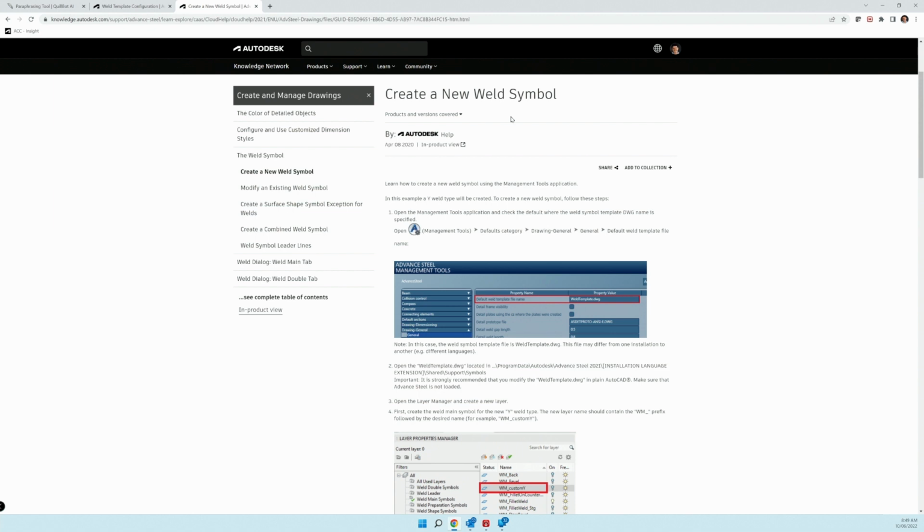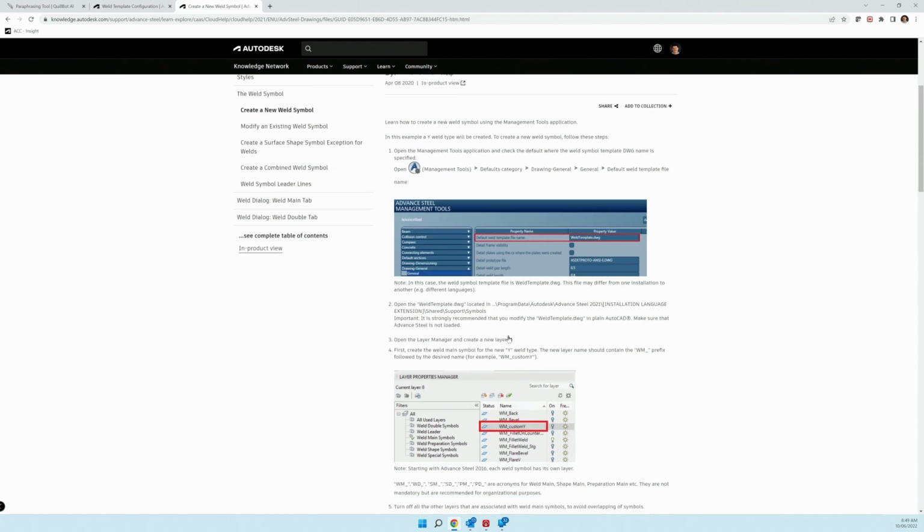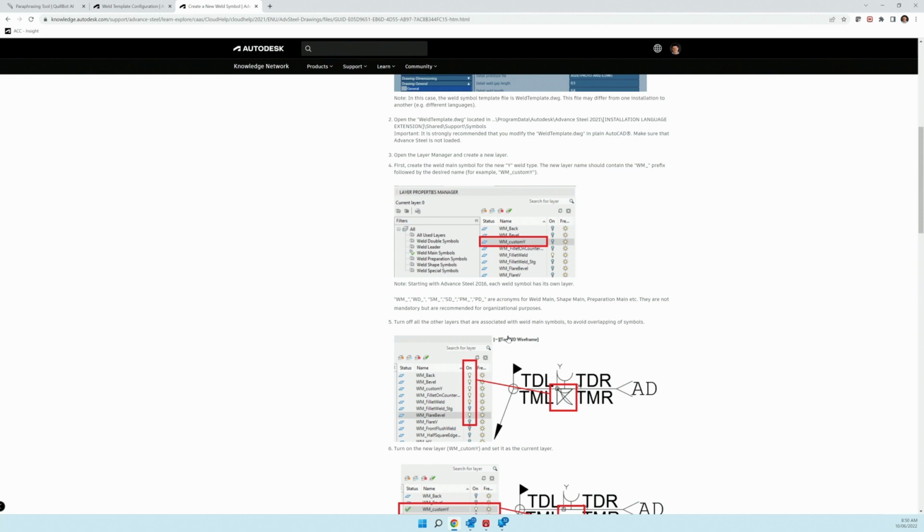Those were weld symbols like the partial penetration type welds, which we call the broad-faced V welds and the broad-faced bevel welds. So we've added those and a couple of others that are actually in the Australian standard which weren't in the out-of-the-box solution. So we've added those into our macro. It's probably a total of about 5 or 6 different weld symbol types that we've added to our macro to improve its functionality.